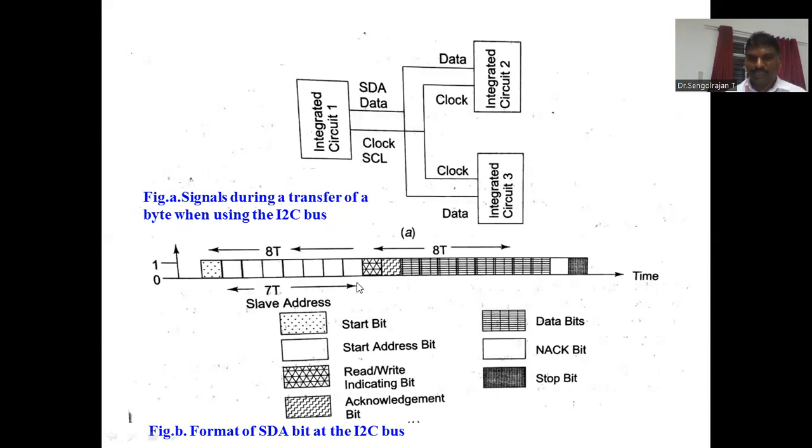Let me take the timing diagram and explain it for a better understanding. In the timing diagram, time is noted along the x-axis and the state along the y-axis. Here, 8-bit data is taken, numbered 0, 1, 2, 3, 4, 5, 6, 7, and 8. Each 8-bit data is separated by an interval and another 8-bit data continues. One 8-bit data is called a frame.